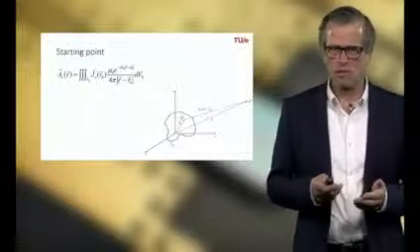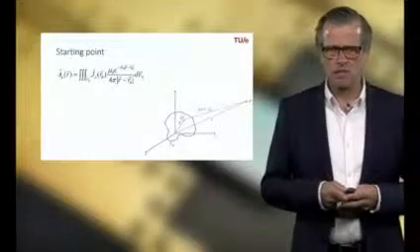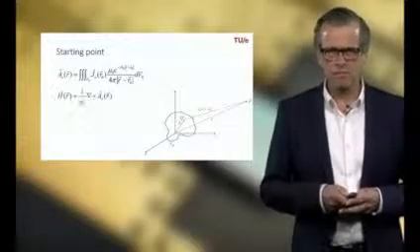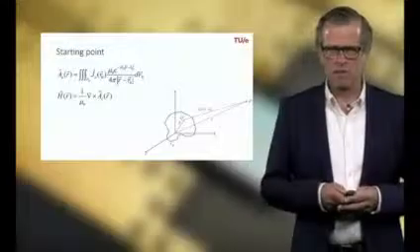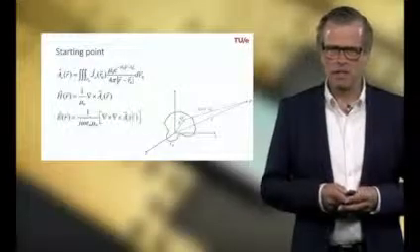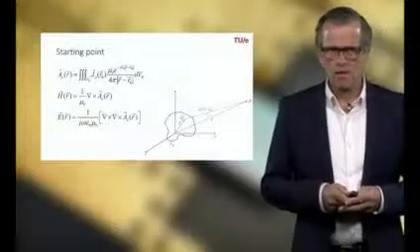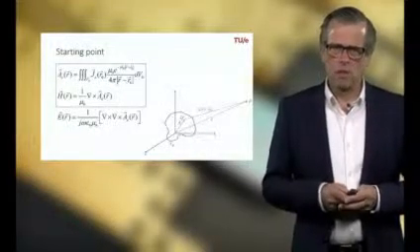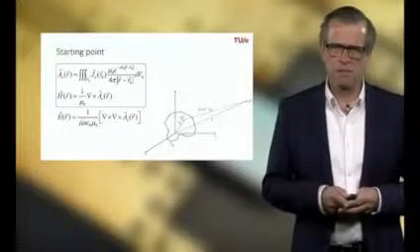Now, we derived the general expression, first for the vector potential, which could be written in this form as an integration over the current distribution and the Green's function. Related to the vector potential is the magnetic field, which can be found in this way, and the electric field was found by this equation. Now, let's first start with the first two equations and see if we can introduce approximations and simplify them.